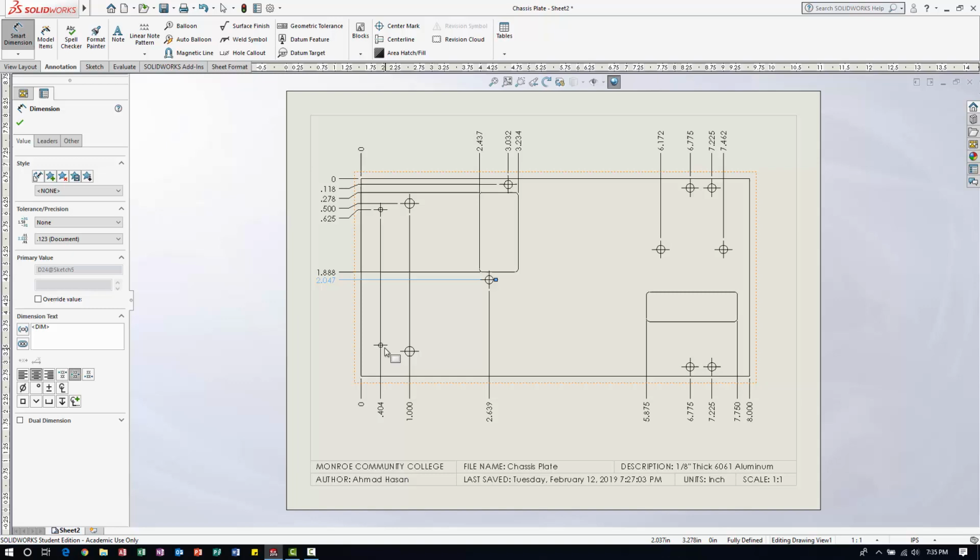Looking at the drawing, we have 3 more dimensions. Have that point, which is 3.375. This point and that last edge. So I have 1, 2, 3, 4, 5, 6, 7, 8, 9, 10. And that's just one way to double check your drawing. If you want to create a drawing that matches an existing drawing, one way is to count how many dimensions you have, to make sure you have applied a dimension for every single feature that you would like dimensioned. So let's go ahead, close dialog.